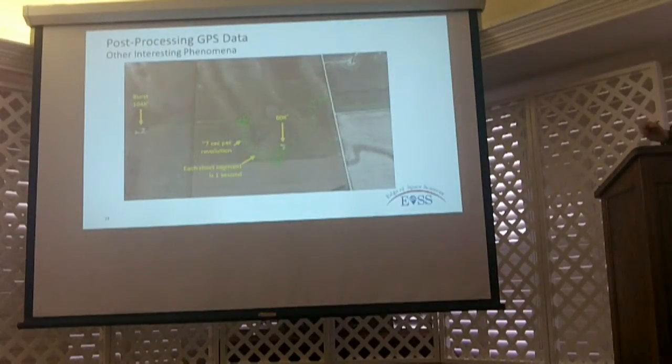The other thing is if we take the GPS data and plot it, we notice this very interesting thing. Over here is burst, it comes down a little bit, and then this payload starts doing circles. We've noticed on these long payloads, when you sit there and watch, you see these payloads swinging around. Everybody's nodding over here. You've seen the same thing, right? This was running about 7 seconds per rotation.